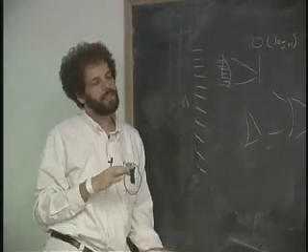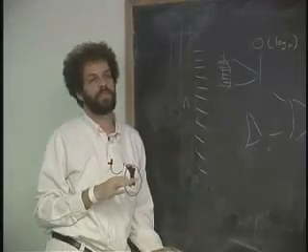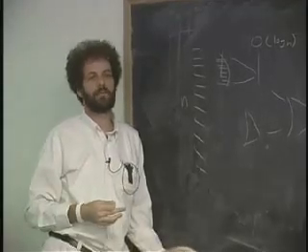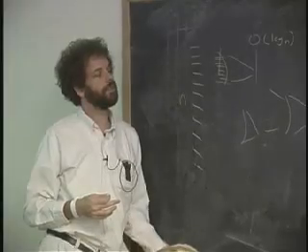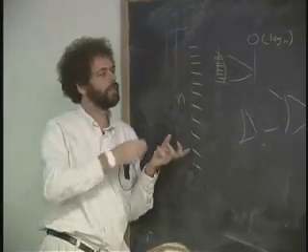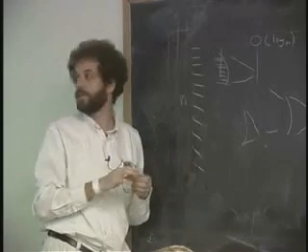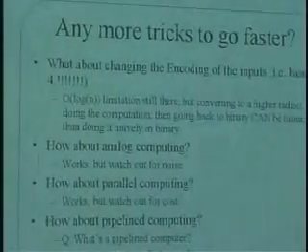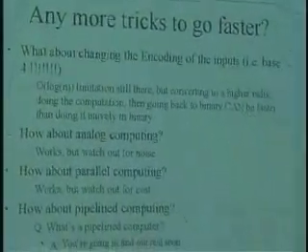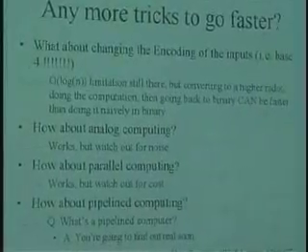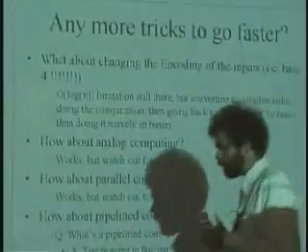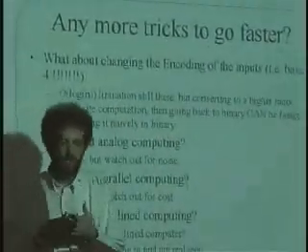But it turns out that n is usually not that big. It's 64, 128, not 10,000 bits. So what that means is that usually the constant factors of the design will dominate. It's basically order log n in theory, but in practice there are all kinds of tricks you can do. I showed you the lookahead of generate and propagate. There are also other tricks where you pre-process the inputs and change what base they're in.